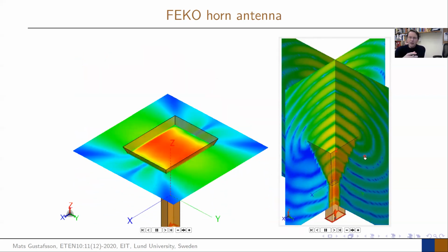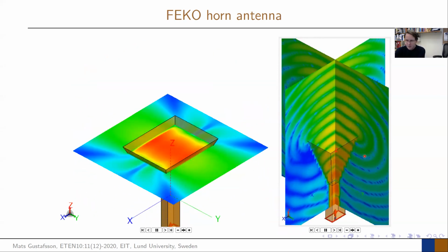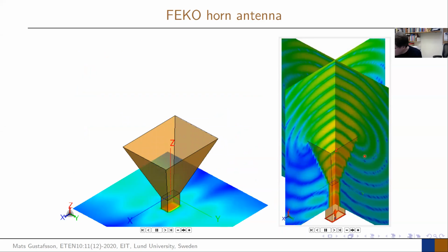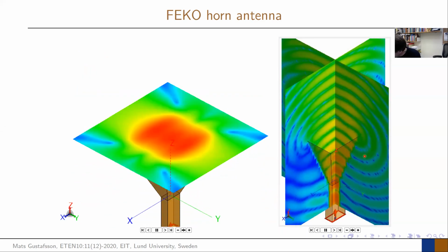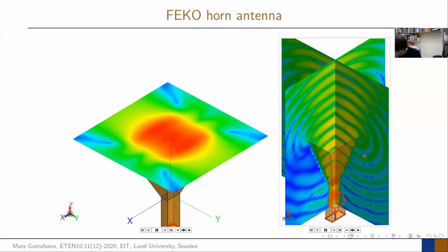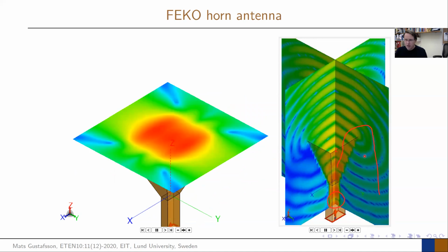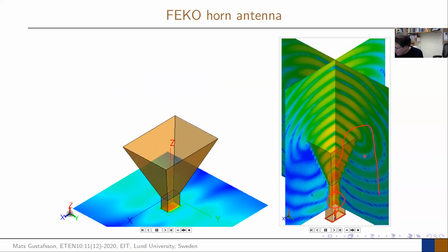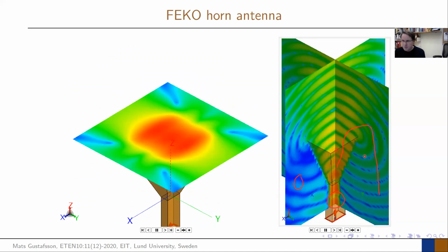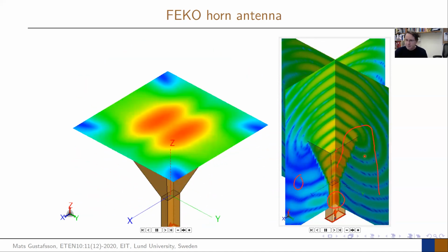And if we make another view of the same thing, and we actually look at the electric and magnetic fields in this horn, you can see the same thing here, because now you see the radiation here again in the waveguide. Here you can see it starts coming out, and basically here it bends around the corner. It's also radiated downwards. In this case, it's almost zero, so it leaks over less to that side.